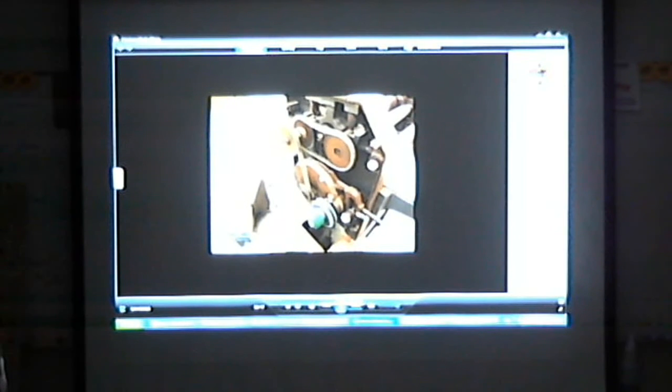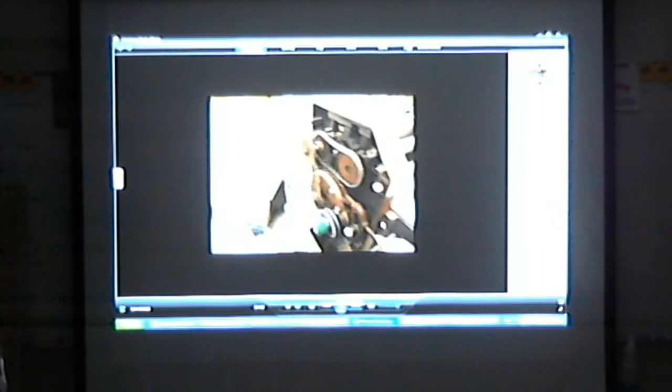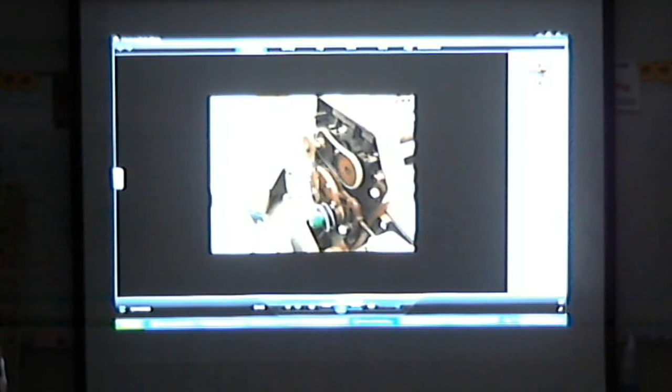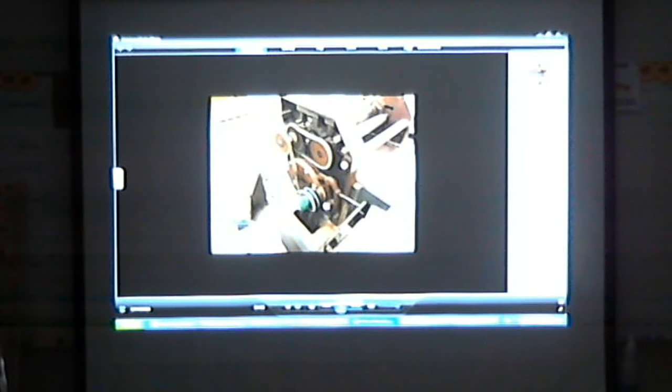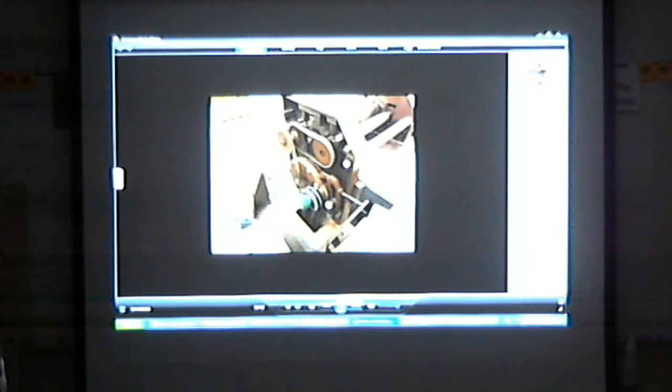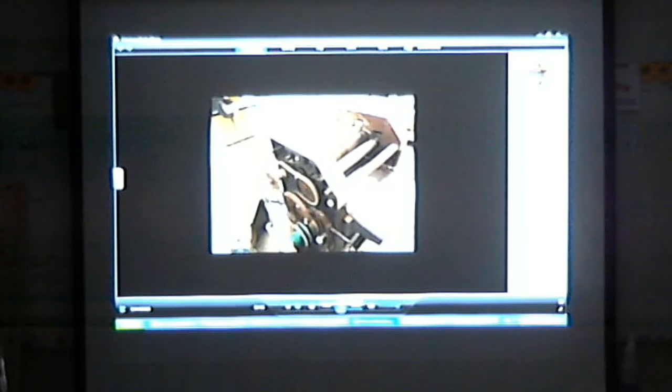This lever here, if there's ever a point where it's not really grabbing your material, lifting it up will adjust the speed. Lifting it up causes the material to go in faster. So it changes the speed on the in-feed roller. Okay?